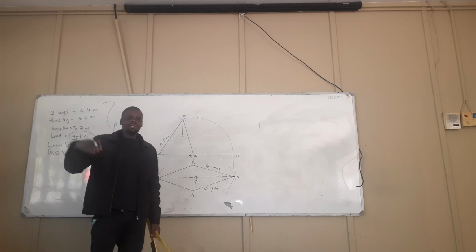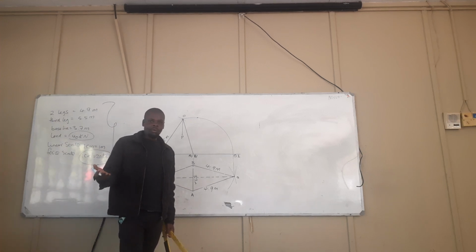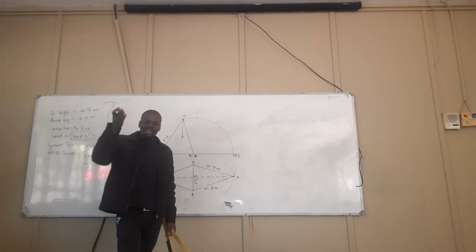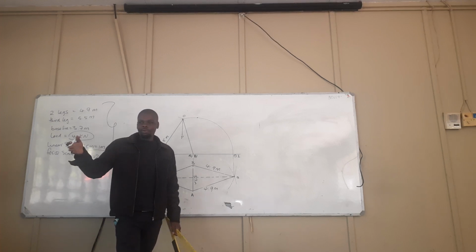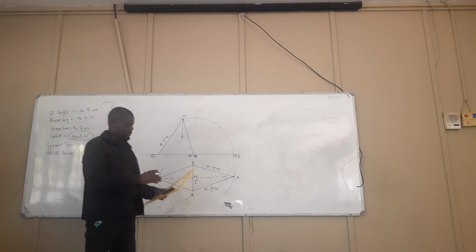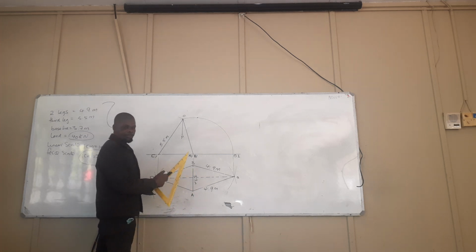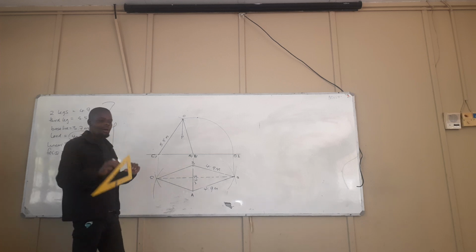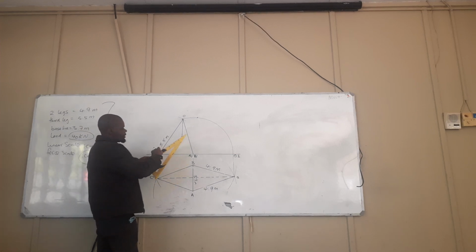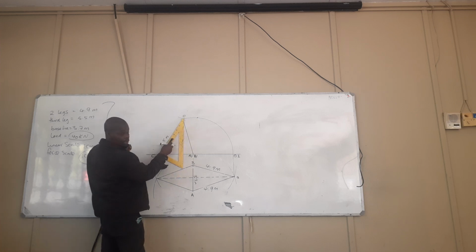Whereby we can get the resultant force of two given forces. We can also, from a given force, find the components of that force. So we want to create a parallelogram. Please make sure that you use your set squares. I think you know that method, right? So from P, I want to draw a line that is parallel to C1, right here.